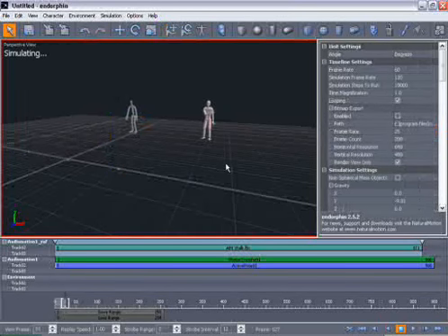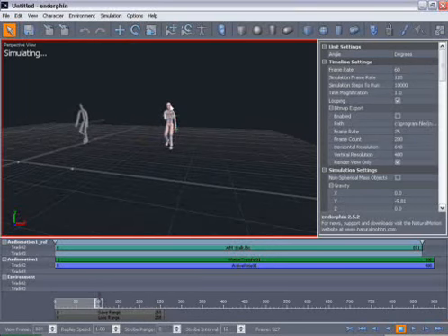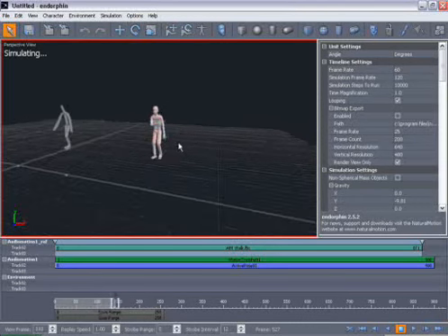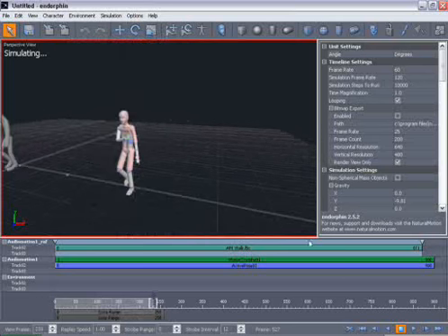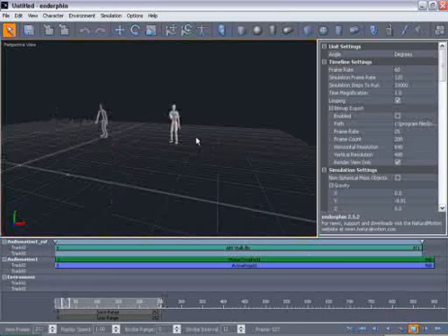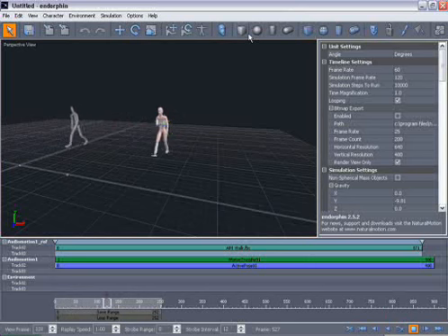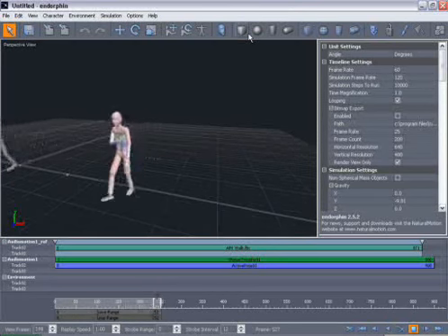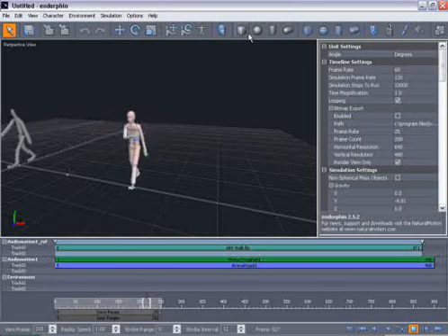And now when I simulate, you can see that the pose pulls his arm down into that angle there to effectively look like he's holding a shield. You can do other things like turning down the strength of the active pose, or indeed adding a mass object to the scene using a join bodies constraint, attaching it to the arm, and see how that affects the motion.